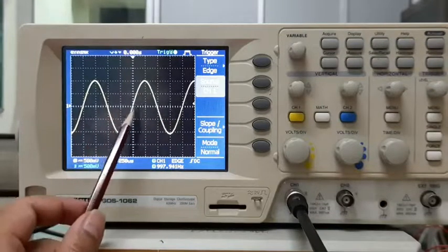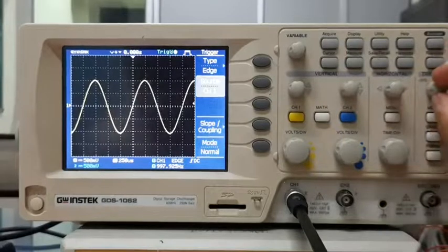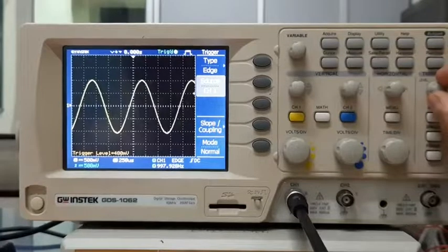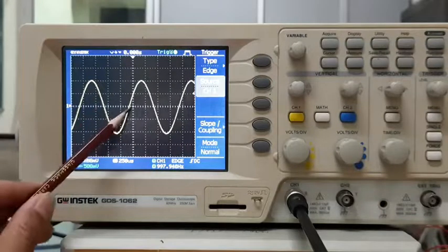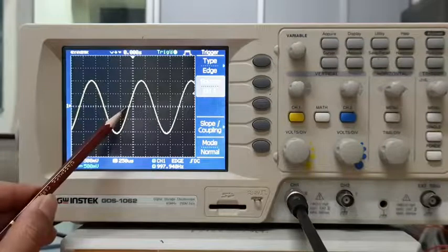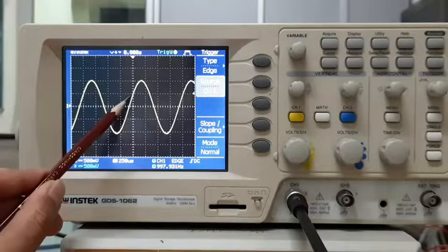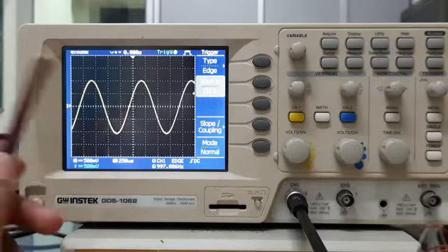There is a small shift of the signal. You cannot see it much because 100 millivolt is still much smaller, but there is a small shift, and what we can do is go substantially higher. So let's say 500 millivolt. I'm now refreshing my display when the signal amplitude crosses 500 millivolts, right? And now you can see that this cross wire does not match with the 0 crossing of the signal. Rather, it matches with the value where the signal amplitude crosses 500 millivolt, right? So that's what the trigger does in terms of display.